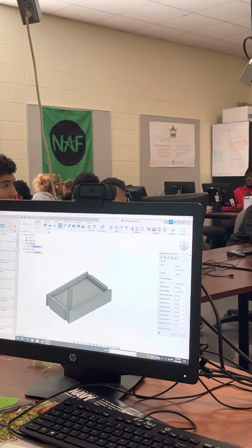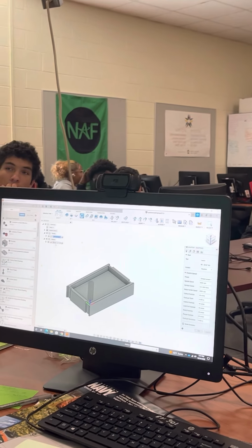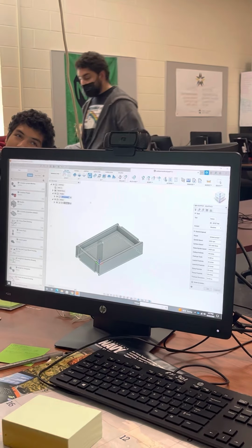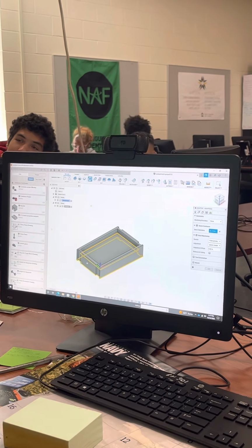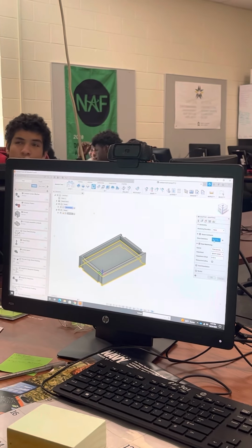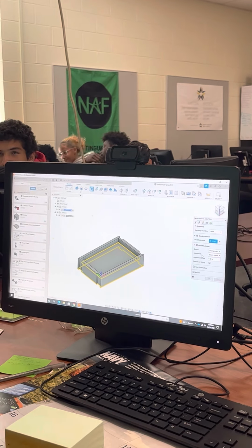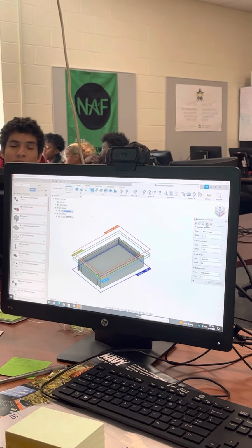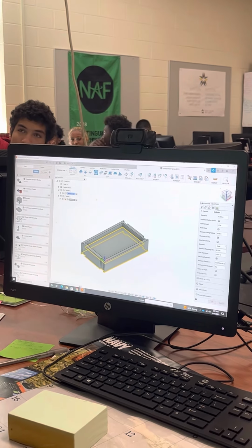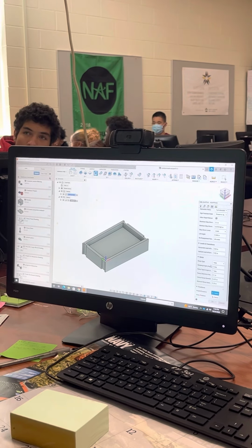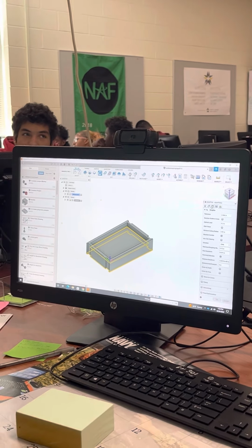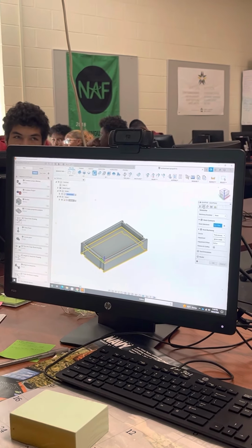And let's see if this lets me choose the whole model and just run it on the whole part. I want it to cut the bottom, I want it to cut the profile. So all this detail in here. We can go back and change these settings later. I don't want any stock to leave, take that off. We might have to go back in here and look at these later. There's a lot of variables to consider when programming the machining process.